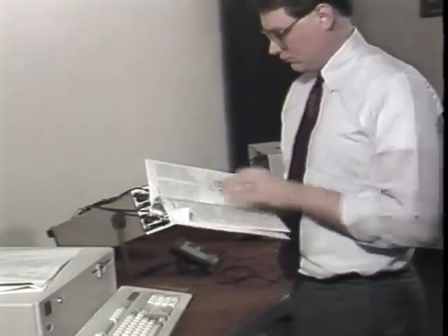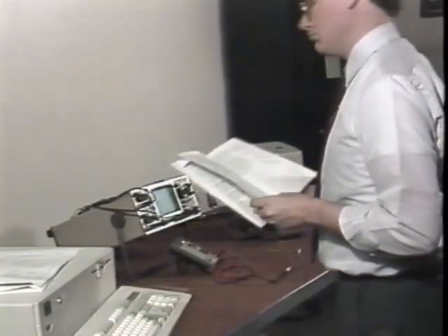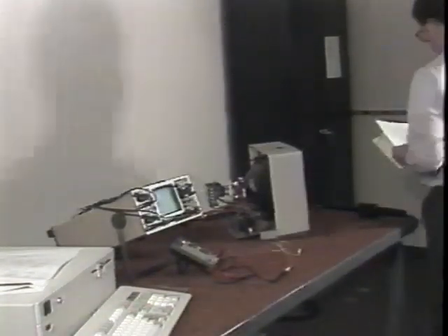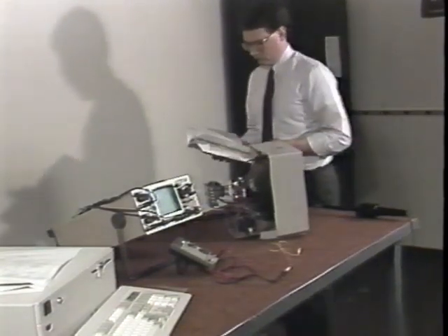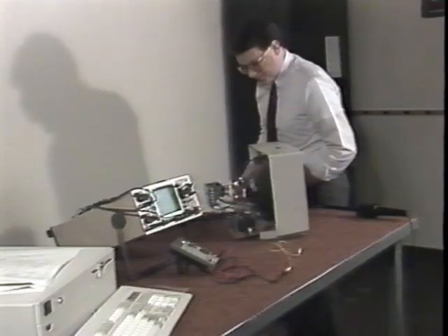Usually you will remove the internal drive controls from the circuit, either by shorting them out or removing a service switch or jumper. This will prevent the drive control settings from affecting the cutoff adjustment. Consult the manual for exact directions. Turn all 3 cutoff or bias potentiometers all the way counterclockwise. This will result in a black screen.